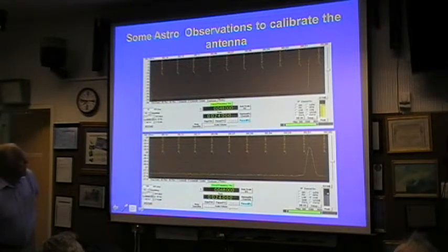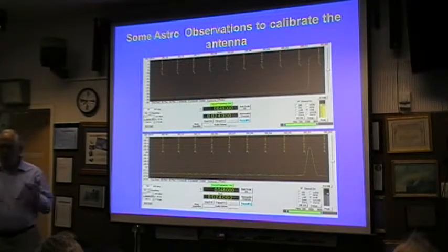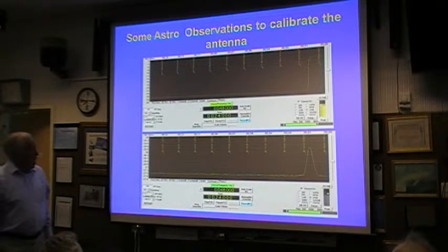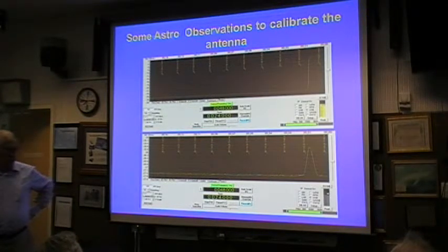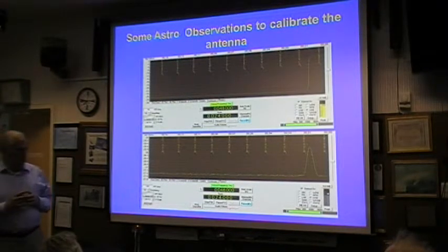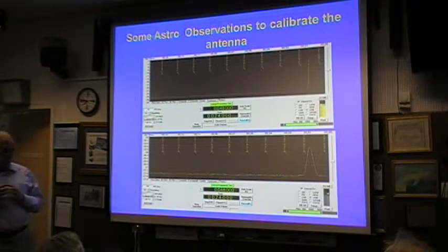And you can see what we've done. We've gone from -27 to about -7, so about 20 dBs of sun noise. Not particularly good, because we haven't got all the right gear in place, but it'll do. Then the next thing you want to do is to calibrate it using a known calibration point. There are various radio stars, as everybody calls them. They're not really stars, they're supernova remnants that are emitting radiation. And astronomers use these and check the flux density, the signal strength, if you will, from these various sources.